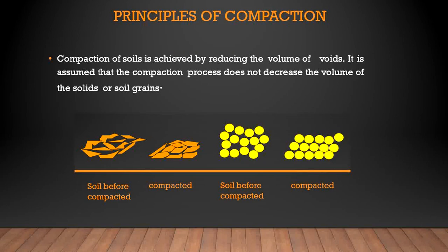Now we will see the principle of compaction. The process of compaction is accompanied by the expulsion of air only, as we have already seen. In practice, soils of medium cohesion are compacted by means of rolling, while cohesionless soils are most effectively compacted by vibration. Prior to the advent of rolling equipment, earth fills were usually allowed to settle over a period of years under their own weight before the pavement or other construction was placed.